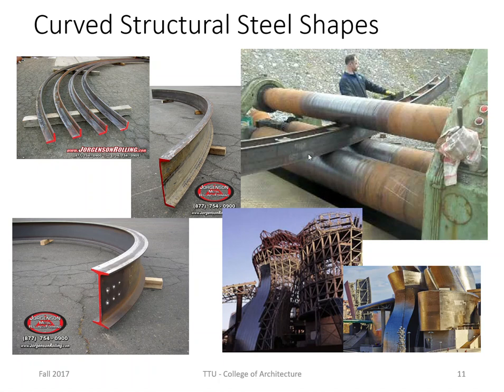But you can notice what they do is they run it through a series of rollers. They have to run it through there and change the degree a little bit every time. And it's done cold. The metal is not hot. It hasn't been heated up. It's just rolled out curved through these rollers that are adjusted to give you the curvature that they want.